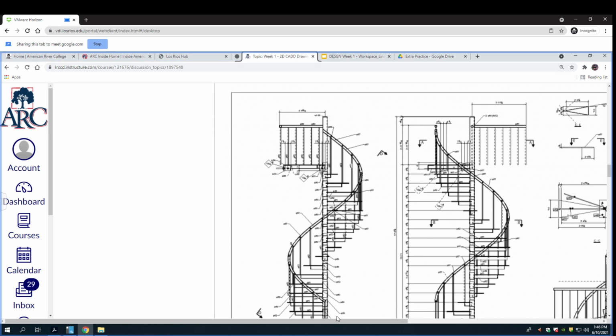And you basically just get to weld this in place, bolt it in place. I doubt if you're going to glue it in place. You could even stack these if you wanted spacers so that the load is all taken really well. And then all you have to do is have a little fixture that sets the angle of each one with respect to the last one.